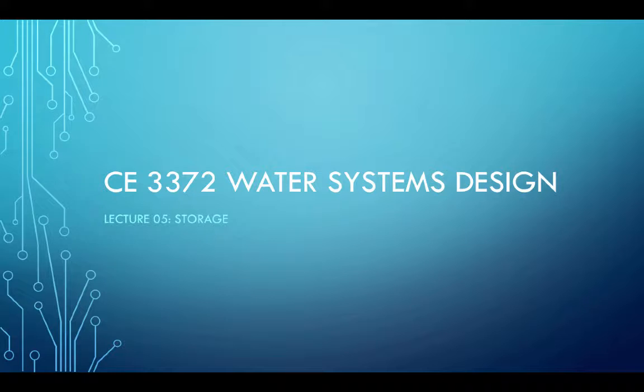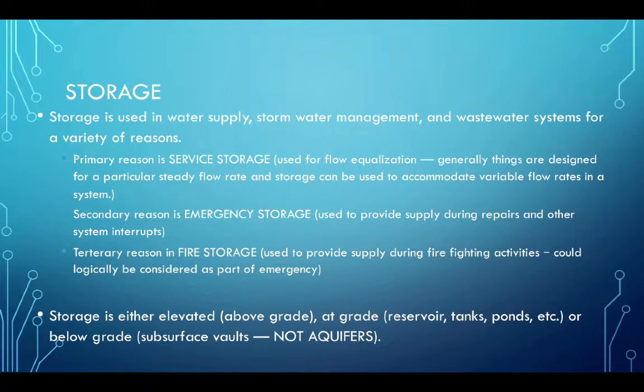The topic of today's lesson is storage and storage concepts as it applies to water distribution systems and a little exploration in wastewater and stormwater collection systems. So storage is used in water supply, stormwater management, and wastewater systems for a variety of reasons. There's three primary ones on the water supply side.